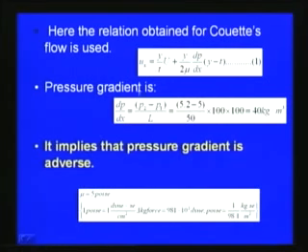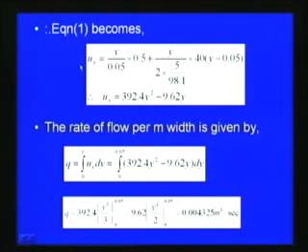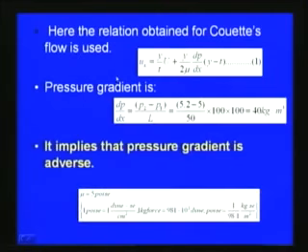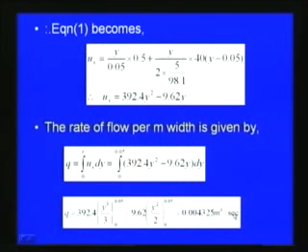Now, the coefficient of viscosity mu is given as 5 Poise. So, that we can write as 1 by 98.1 kilogram second per meter square. We are converting everything into the MKS system, and then finally we can substitute back into the equation. Now all the parameters are known here, so we can get an expression for the velocity. So, u_x is equal to, in the previous expression, this t is 5 centimeter, so 0.05, and U is 0.5 meter per second, and dp by dx is obtained as 40, and t is also 5 centimeter, and mu is 5 by 98.1. So, now we can substitute back.